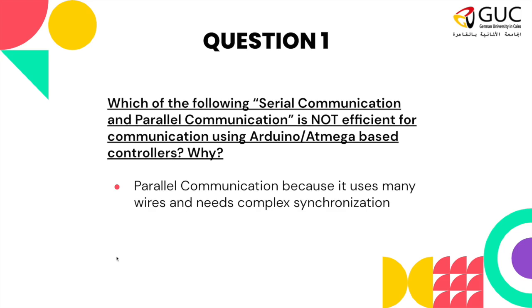Remember, regarding the Arduino Uno board and the Atmega 328P microcontroller, as you know from the midterm exam, the Arduino Uno does not effectively use all of the Atmega 328P pins. Instead of using 8 from port D, 8 from port B, and 7 from port C, it uses 8 from port D, 6 from port B, and 6 from port C.